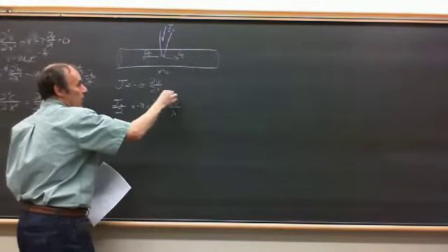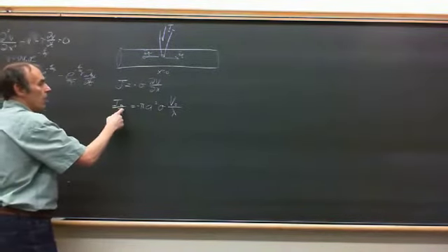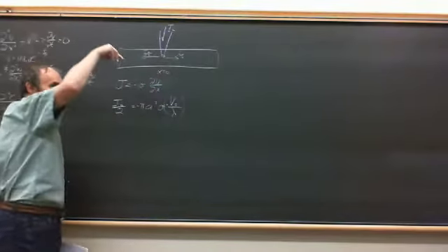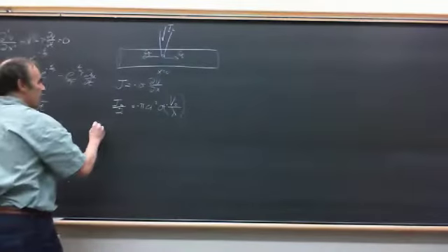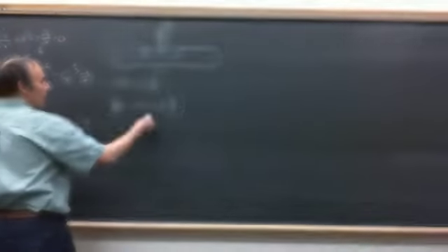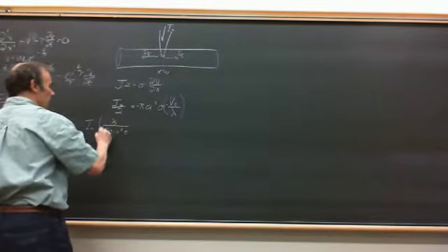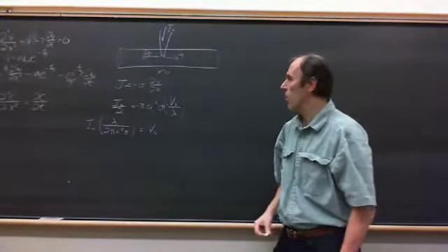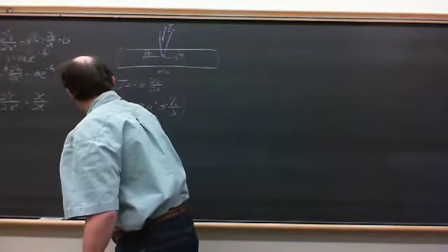That part you're going to have to just verify from your notes. But the factor of 2 is right here, and you also get a minus sign when you evaluate dV/dx because it's going down. So the 2 minus signs cancel, and you end up with this expression. And then if you move everything over to the other side, you'll get lambda over 2 pi a squared sigma equals V0. This looks just like Ohm's law, V equals IR. This thing is the input resistance.